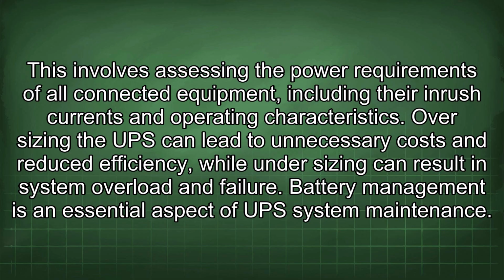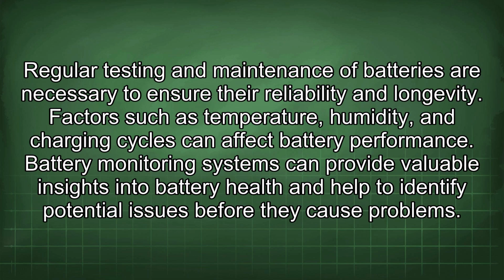Battery management is an essential aspect of UPS system maintenance. Regular testing and maintenance of batteries are necessary to ensure their reliability and longevity. Factors such as temperature, humidity, and charging cycles can affect battery performance. Battery monitoring systems can provide valuable insights into battery health and help to identify potential issues before they cause problems.